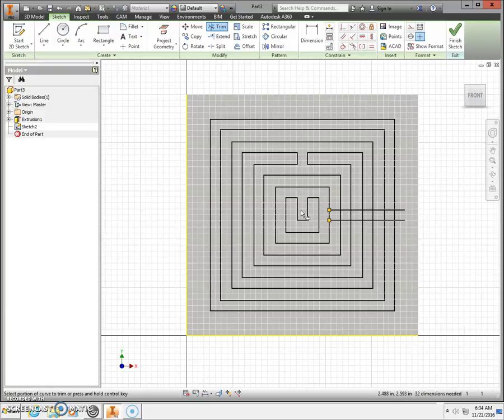This one here, we're going to come out of our box. We're going to cut through this wall here. This wall we're going to skip. And this wall we're going to cut through as well. Get rid of the tags on the end. That's looking good. Line tool again, we're going to come straight down.